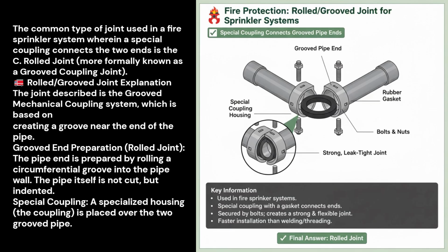Why is double hub pipe best for cutting? If you cut a double hub pipe, both resulting pieces will each have a hub. This allows flexibility in installation. One piece can connect backward or forward as needed.